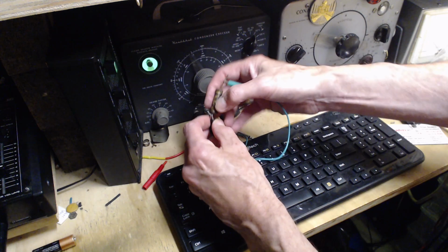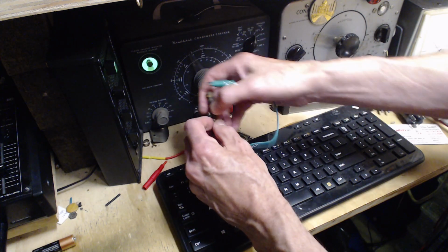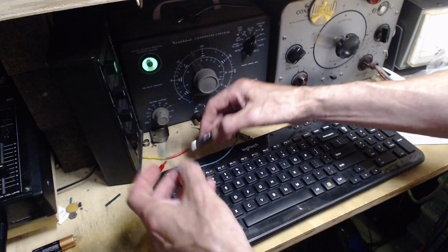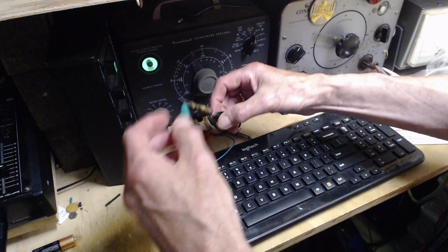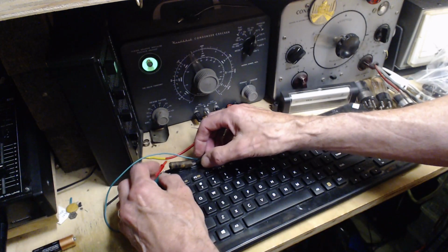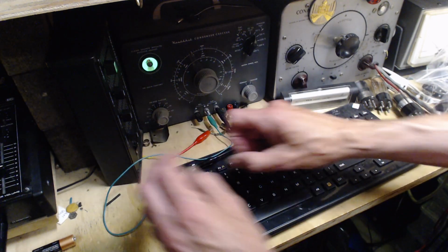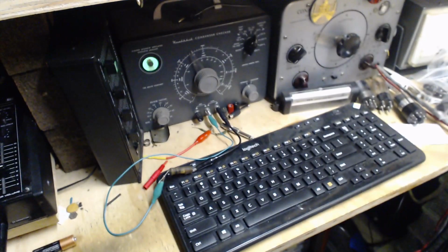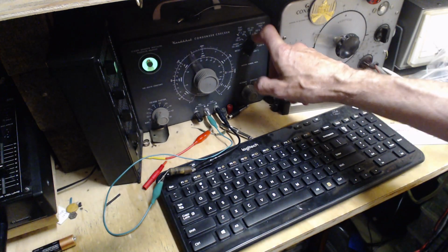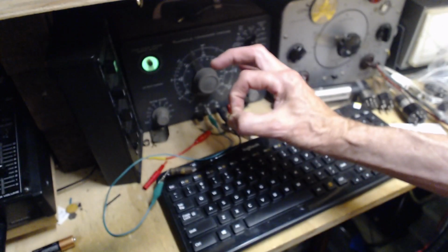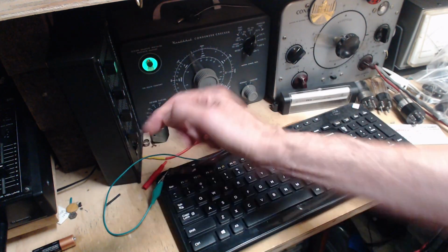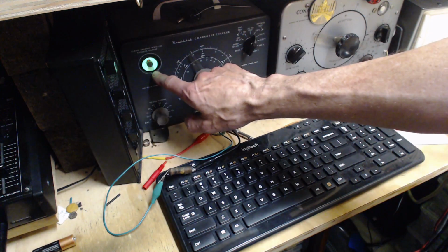So what we're going to do with this device is we're going to put a DC voltage on it. We decide how much. Where's the burn part? Right there. We decide how much voltage with this control, and then current leaking through the capacitor, which should be 0 if it's good. Any current leaks through the capacitor will cause this magic eye to close, which I know is hard to see in the camera.